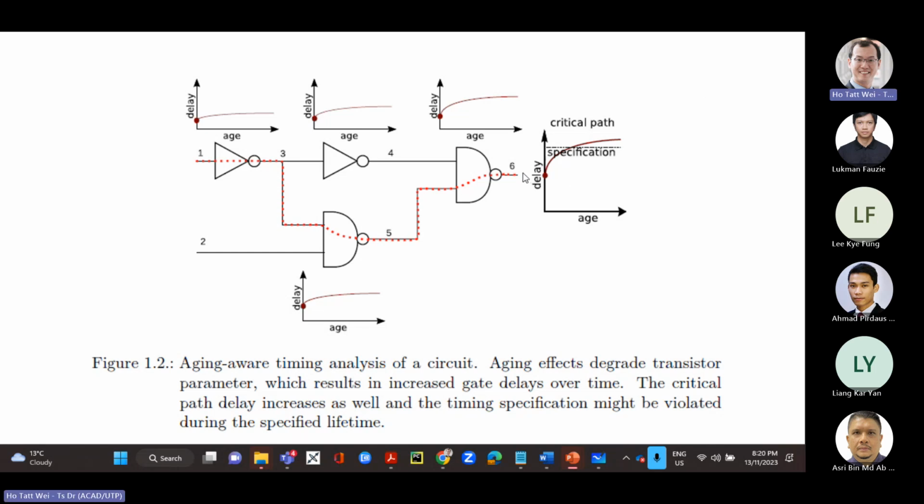Right. The second effect, of course, is what happens to the wires. The wires actually get damaged over time, and they lose their ability to carry current, and in the worst case they just kind of disconnect. So there are two bad things that happen as a result of aging. One is the gates actually will get more and more delayed, and at some point, some of them will actually fail. This will be the dielectric breakdown. We'll talk about that. And the second effect will be the wires will actually degrade, and that also increases the delay of the wires, but at some point they may actually disconnect. They degrade, it reduces the ability to carry current and all that.